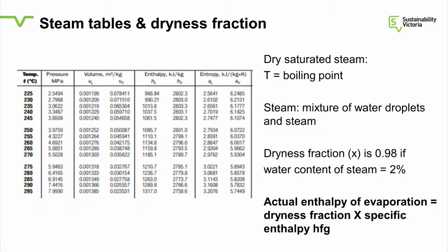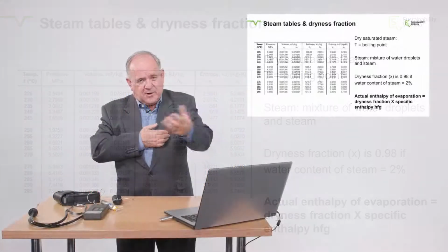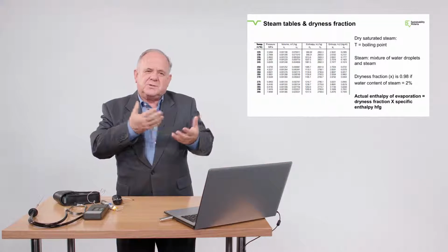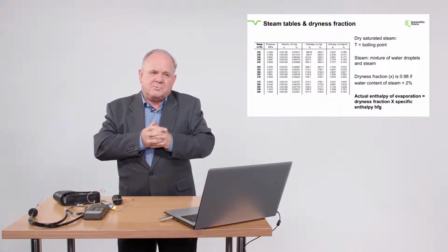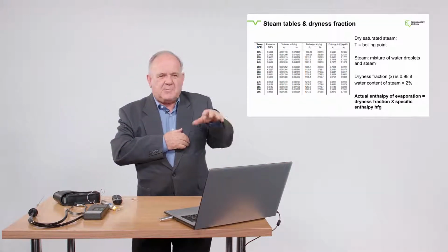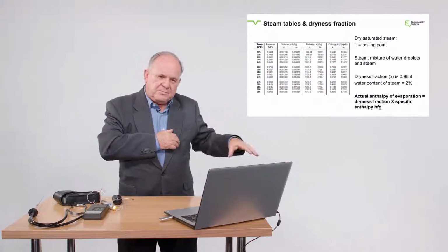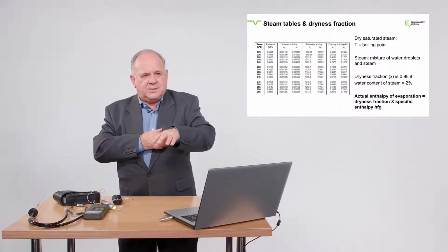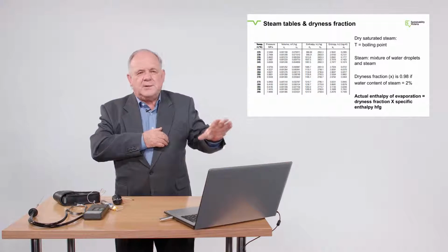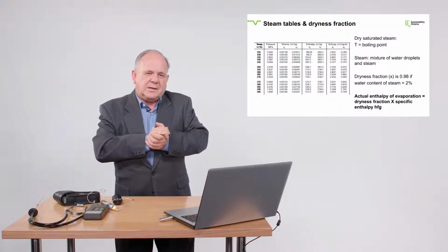It also tells you what's called enthalpy, or the kilojoules per kilogram of steam. And you'll see at different pressures, the amount of enthalpy in the steam for the fluid and the gas, the steam component, varies. So you can use that to determine the efficiencies of the boilers at different pressures and how much energy is in the vapour form and how much energy is in the steam form. So just one table virtually tells you all of that.